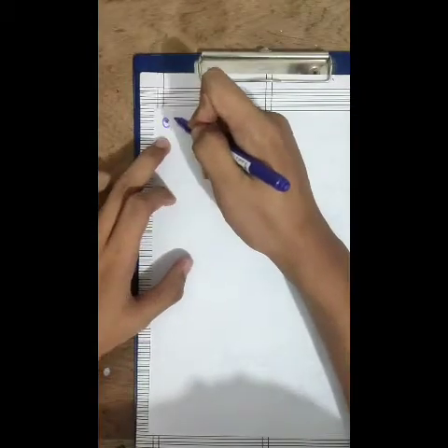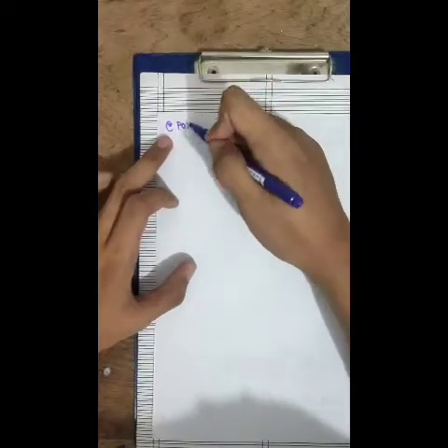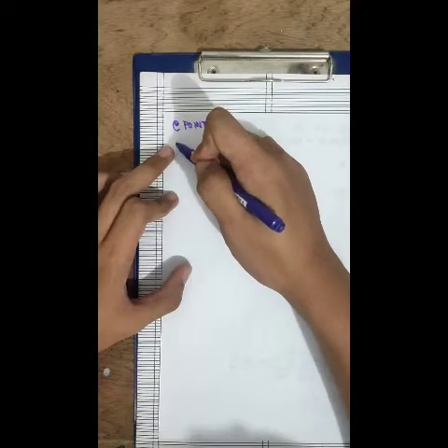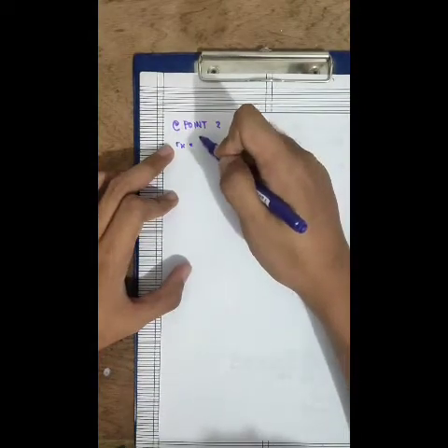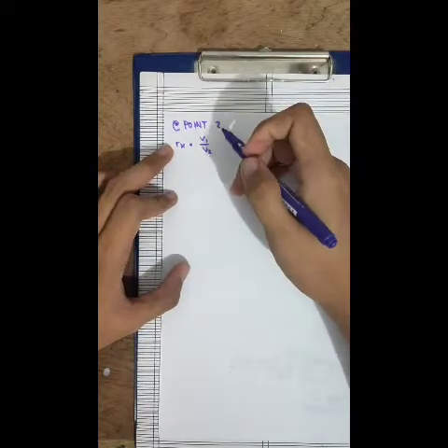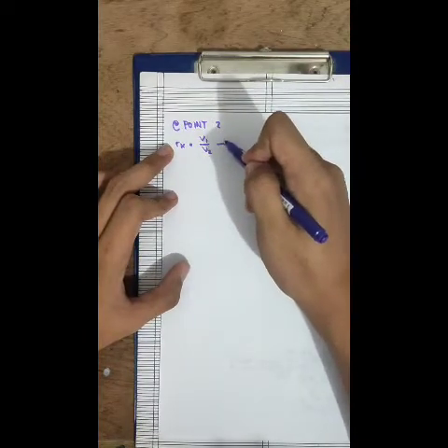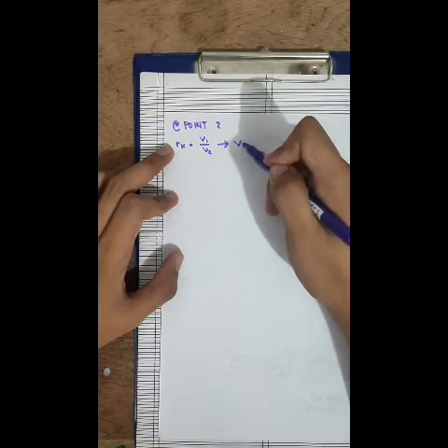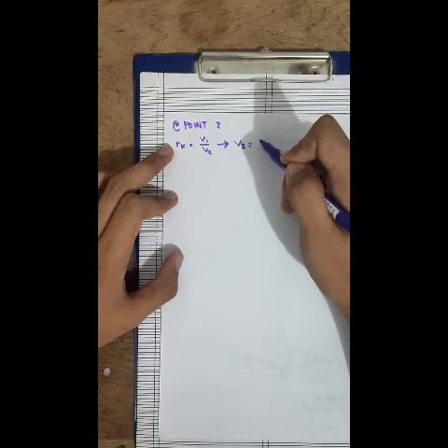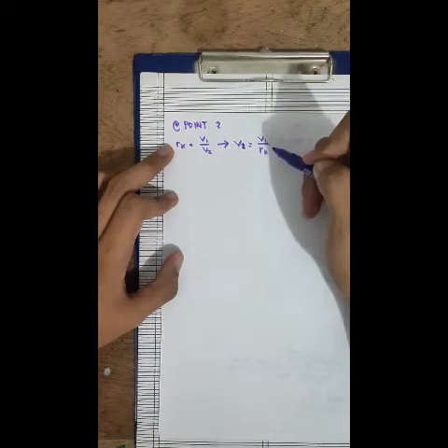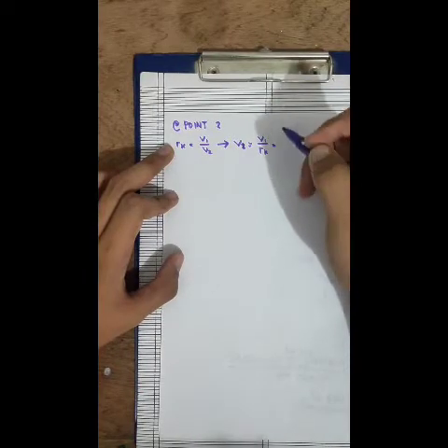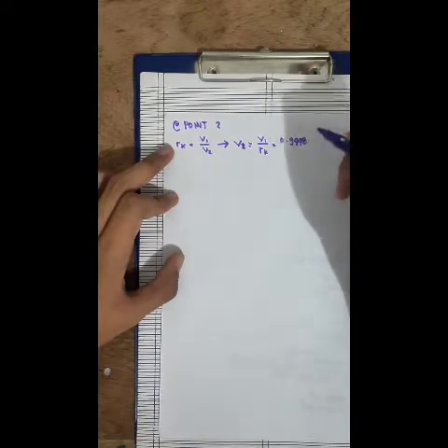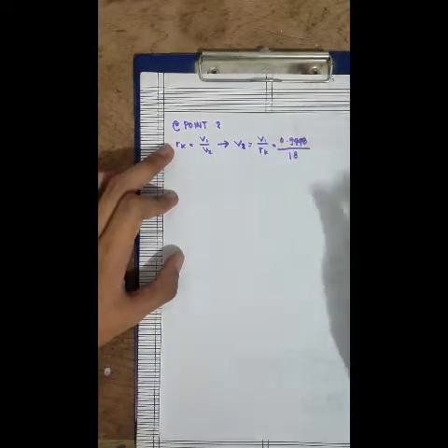So next one is finding the V2, P2, and T2. We can get this from point 2 of the cycle. First we use this equation, RK is equal to V1 over V2, and from this we can get V2, which is equal to V1 over RK. We substitute the data here, 0.9448 over 18.